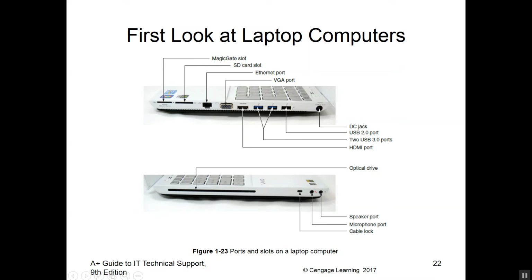That's where our DC or direct current power feeds this unit. Now, the difference being, in a desktop system, the power is converted inside the power supply. You've got a cable that comes from the wall to the power supply, and then the power gets converted inside the power supply itself. Now, when it comes to a laptop, the power is converted usually about a third of the way through the power cable. You'll see a little box, rectangular in shape, and that converts it from 110 volts AC down to a DC current.